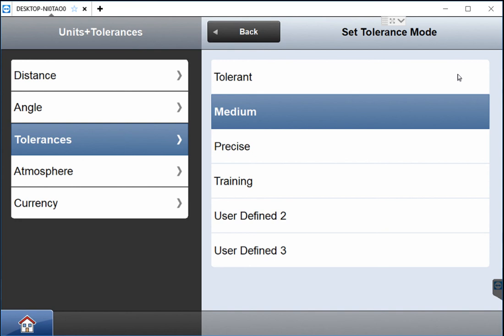There are several reasons why this may happen. To name a few, your total station may not be level. Your rod may not have been level when you measured your point. The tip of your rod may not have been precisely on the point. Your rod's level bubble may be out of calibration. You may have the wrong prism type selected. You may have accidentally selected the wrong point from the map view as your target.